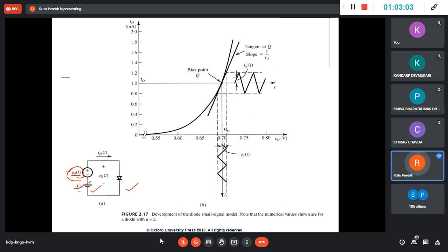It can be made on by this signal also. That can be your question: why do we need to turn the signal on? But you must remember, if you are processing a signal, let's say from a sensor, that is really a small signal in millivolt. If you don't have this bias voltage here, and you just give millivolts to the diode, it will always remain dead.